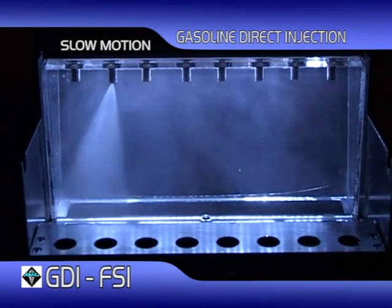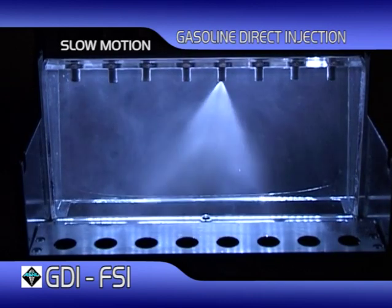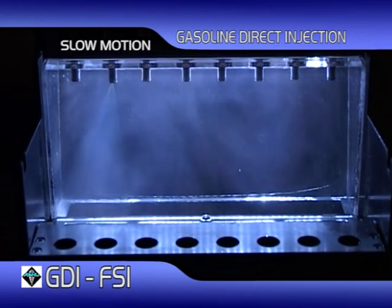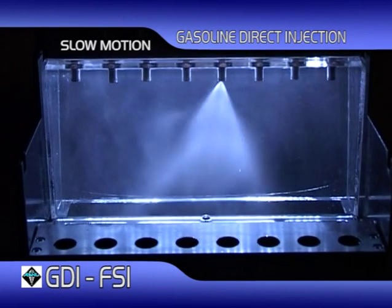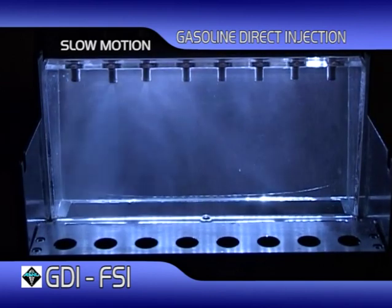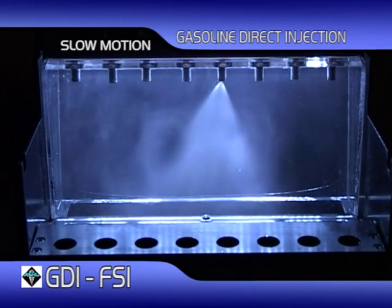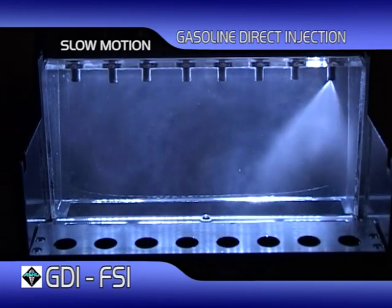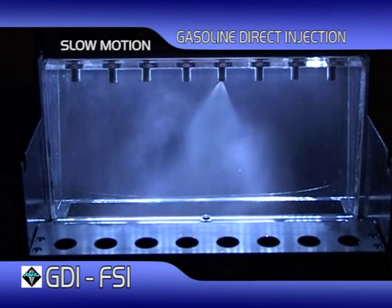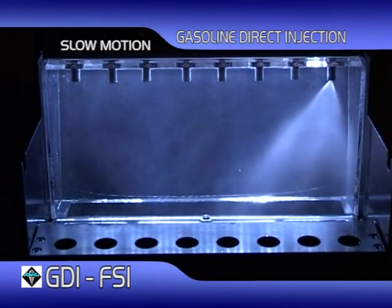Even if the injector's electronic operation is not showing a fault code, the injector, and in particular the fuel distribution and atomization, can still be responsible for a fault code further down the stream. Here you can see different shapes of spray distribution and strengths of atomization. If these were fitted to an engine, it would have some running and performance problems.